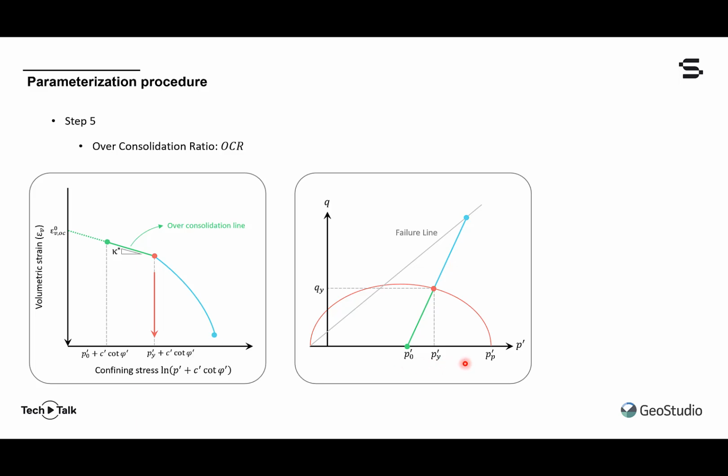As stated earlier, the response of the specimen changes from elastic and overconsolidated to elastic plastic and therefore normally compressed only if the stress path touches the yield surface. As a result, for a stress path that is not necessarily isotropic, the yield pressure p′_y is less than the isotropic pre-consolidation pressure p_p. These two pressures, however, are not independent.